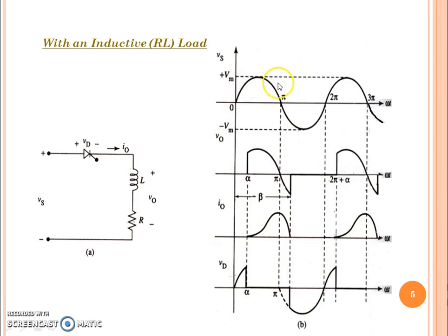During the positive half cycle, this thyristor is conducting, so we can have an output voltage like this. In this waveform, the firing angle is followed, so from 0 degrees to alpha we don't have any output voltage V0. But from alpha to pi, there is conduction. There is output voltage from this half-wave controlled rectifier.